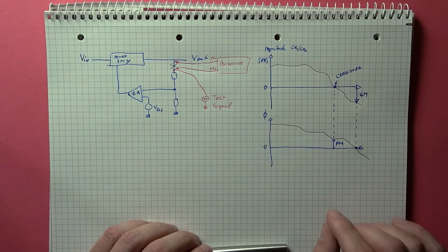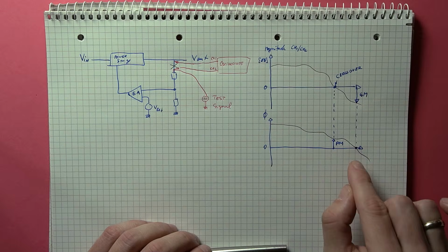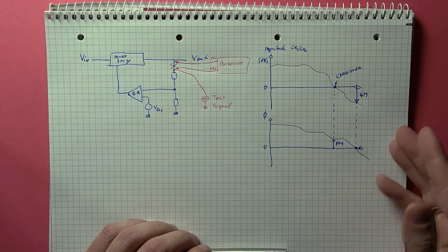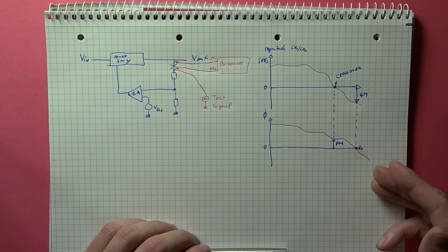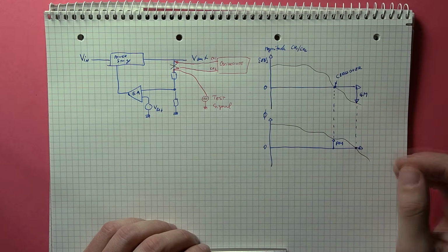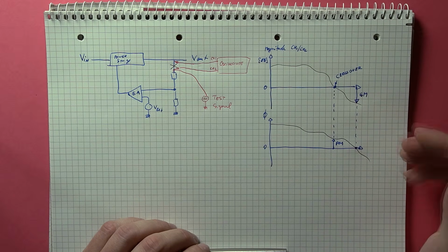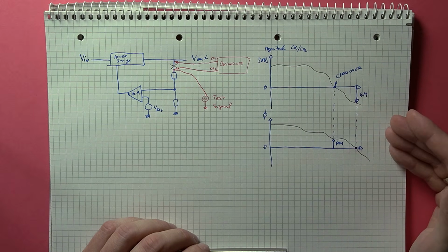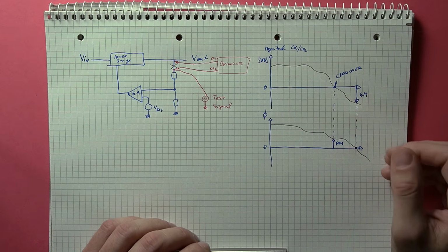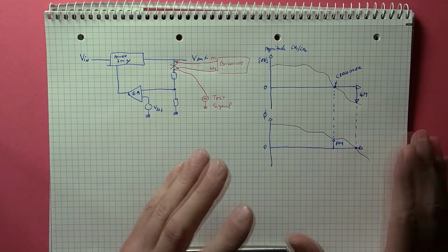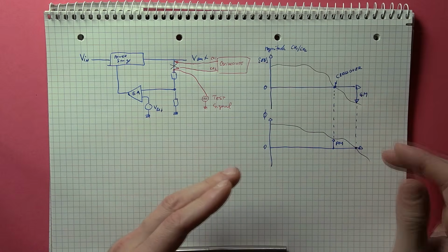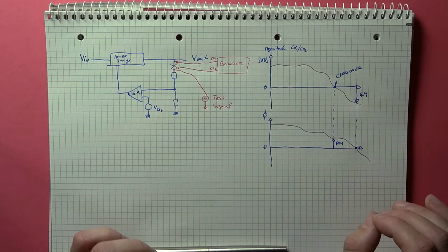Now, another important point on the graph is the moment when the phase does pass through 0 degrees. Ideally, you want to have subunity gain at this point, but the lower the gain, the better. So this is referred to as the gain margin. Again, as a rule of thumb, values lower than -10, -15 decibels are recommended.